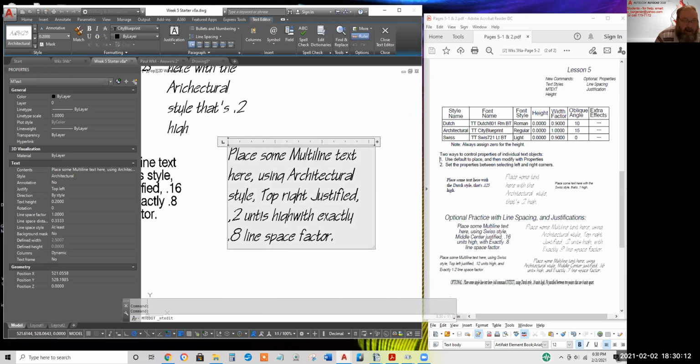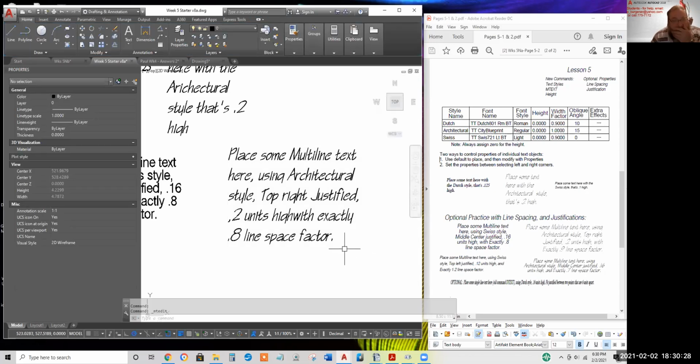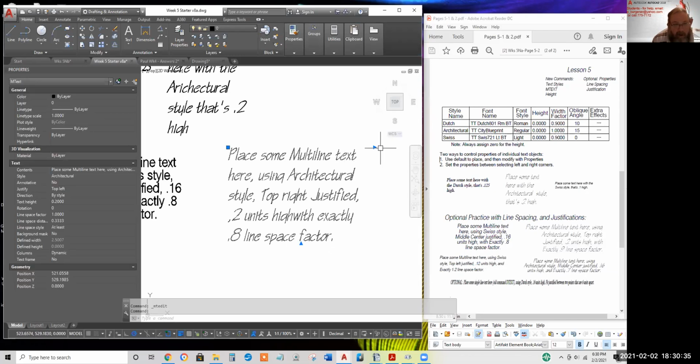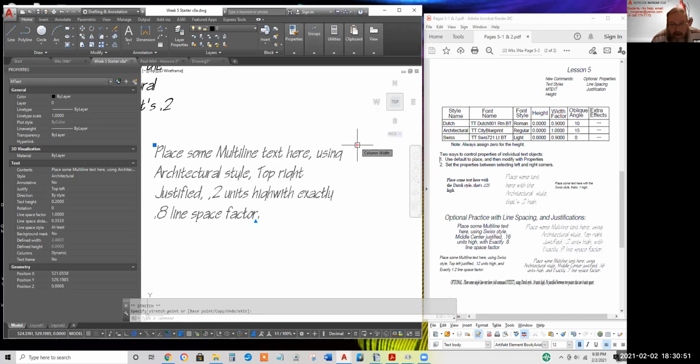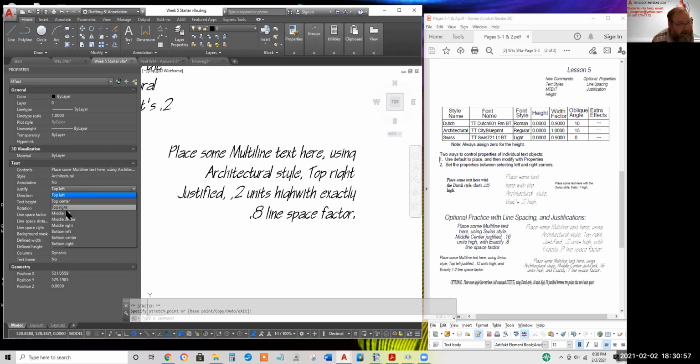Double click to fix the spelling. I think there's a way you can rig your AutoCAD so literally Word is your text editor, but I'm not smart enough to know how to do that or really see a need. All right, we'll grip edit it, tweak the right margin. Got the first line looking good. While it's still selected, change top left to top right.